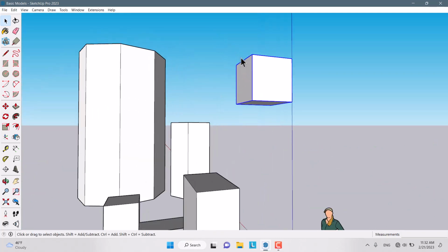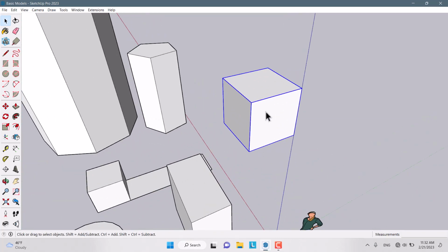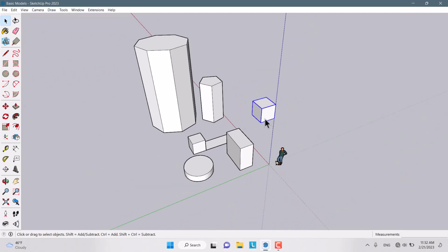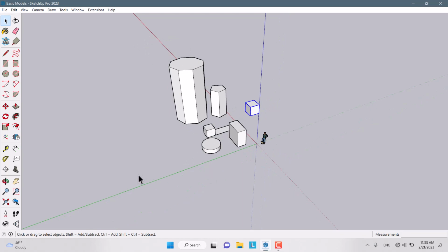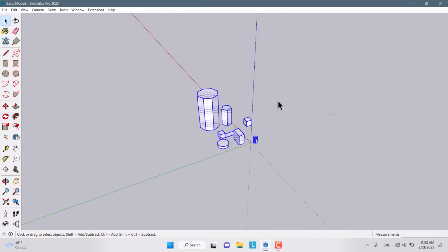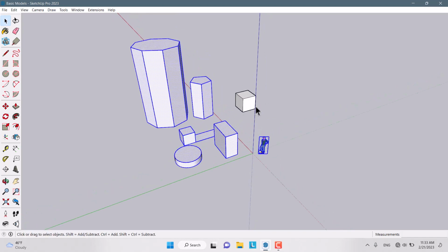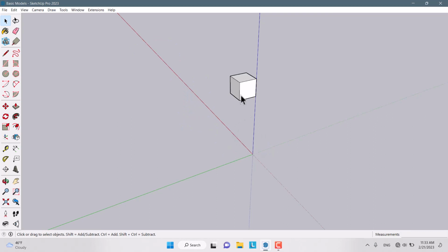And now we can make lots of changes on our models. For example, I just want to keep this and delete all of this. Very simple and easy. I choose all of these objects like that. Left click plus drag: hold the left click and draw this window. And I hold Shift and select this cube, so this cube is deselected from the others, and I press delete.